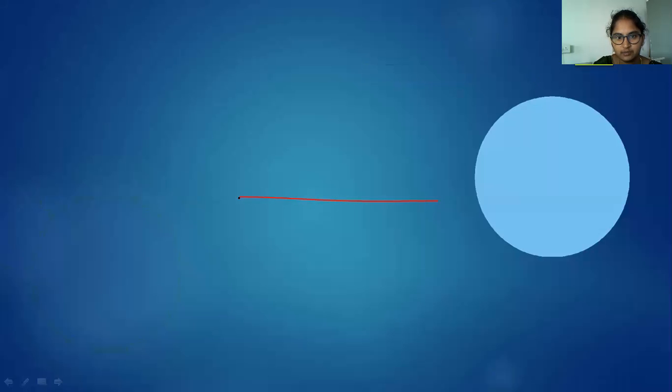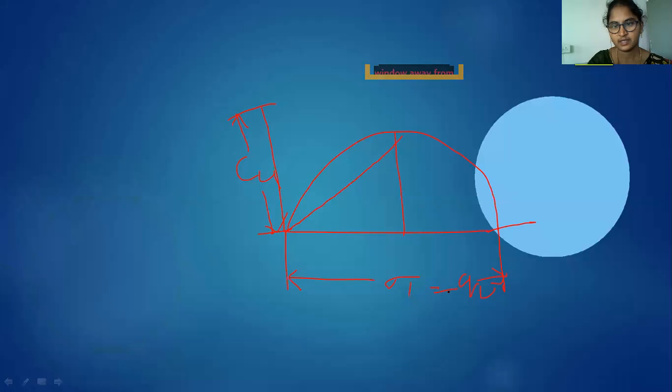Draw the graph this way with the total stress axis, the center at c. Sigma 1 is equal to QU, and tau is equal to QU by 2. Here phi is equal to 0, and this is the failure envelope.